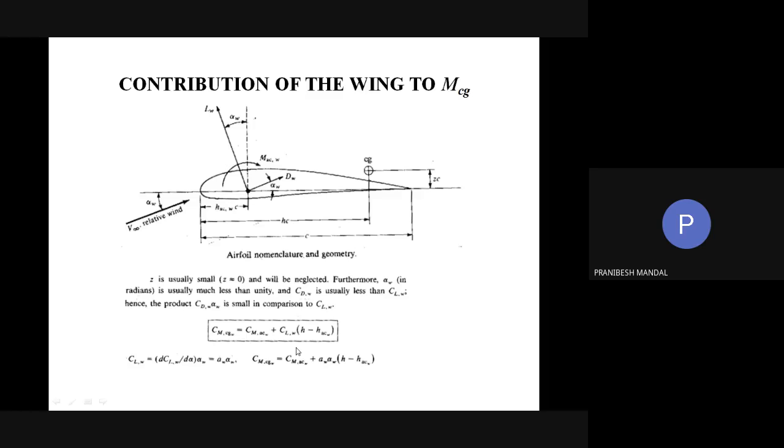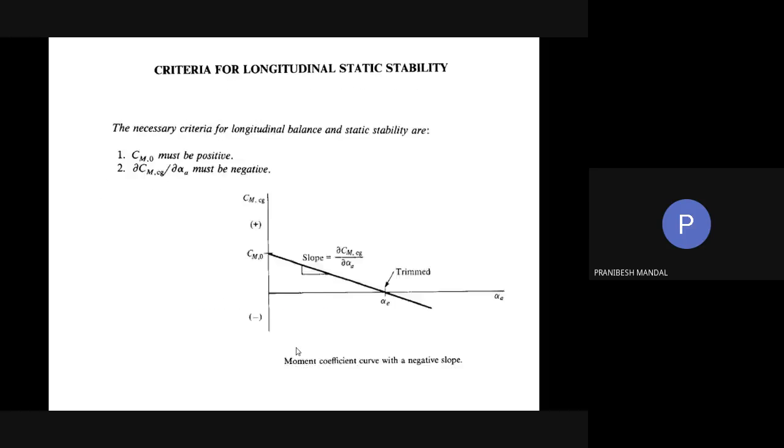And what is the function? As we all know, the curve between CL and alpha is a straight line up to a certain limit. And obviously for our case, the trimming condition, CL must be well within the stalling limit. Isn't it so? Yes, sir.